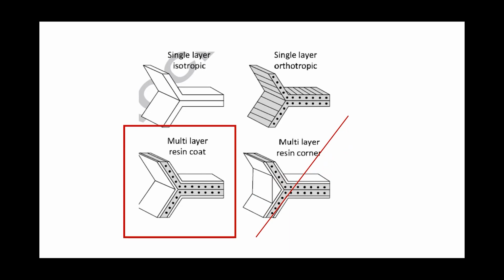I don't know if you noticed at the beginning when I was showing you how the manufactured Nomex core looks like, due to production reasons, you will always have resin leftovers in the corners. At this stage of the analysis, we didn't take this into account, but unfortunately, it appears that they will have some impact on the final dynamic results.